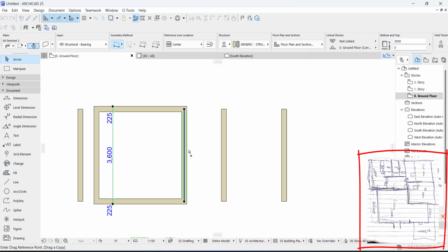Okay, it will give you this plus sign, which means you can actually move a copy. The same way if you want to rotate, Control Shift E, it will give you this plus sign and this rotational symbol. It means you can rotate a copy.